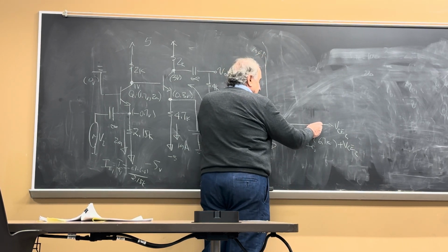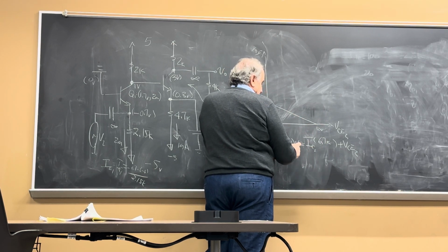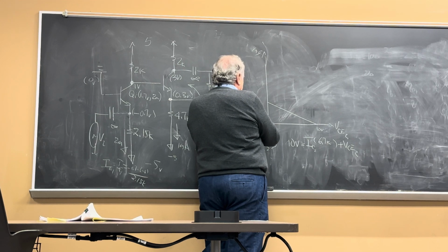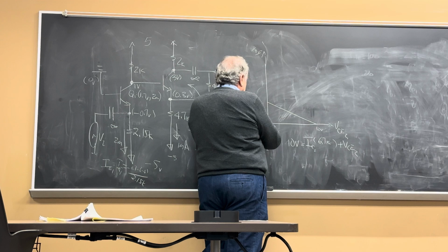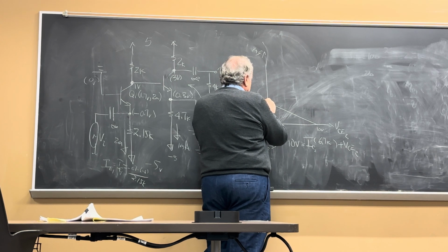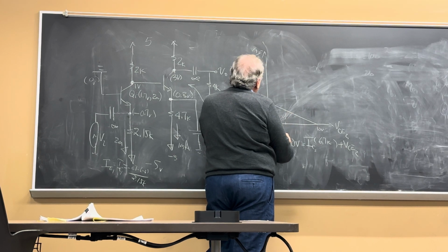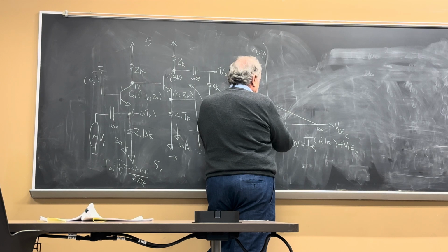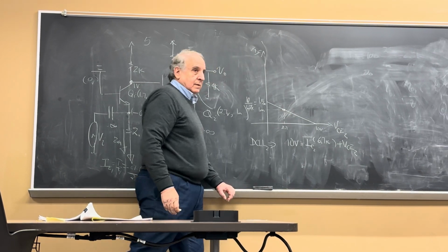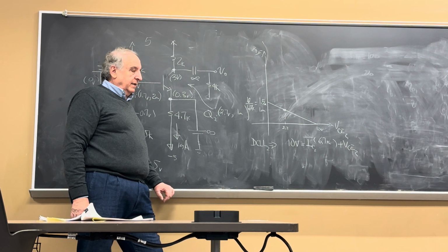So you plot this, you get 10 volt, and you get this to be 10 divided by 6.7, okay, it's 1.5 milliamp. And the Q point is here, 2.7, and this is 1. Right? Now the AC load line.